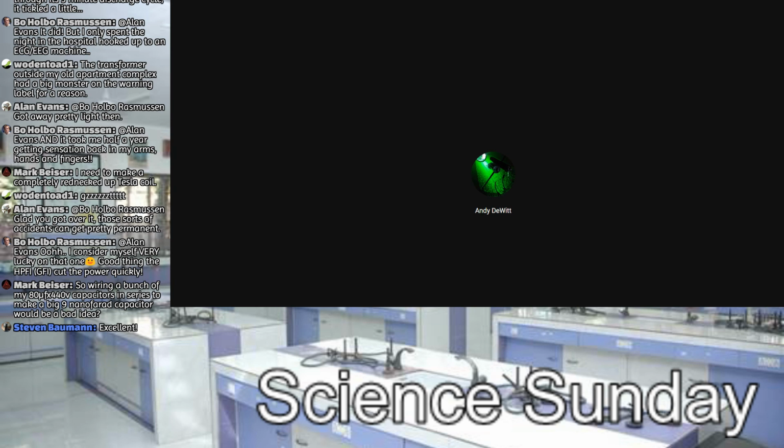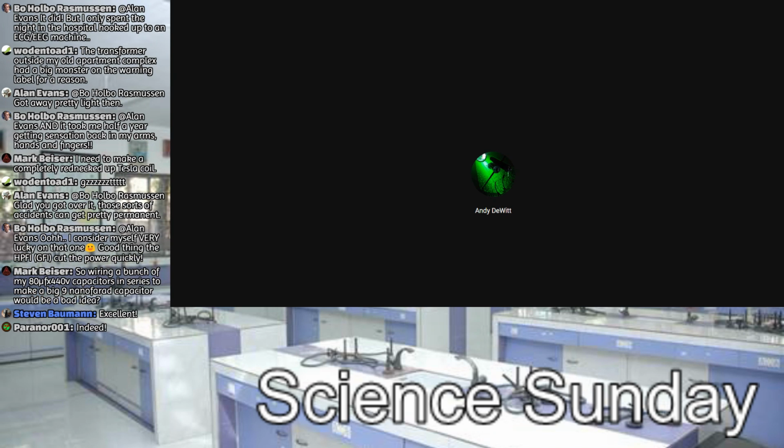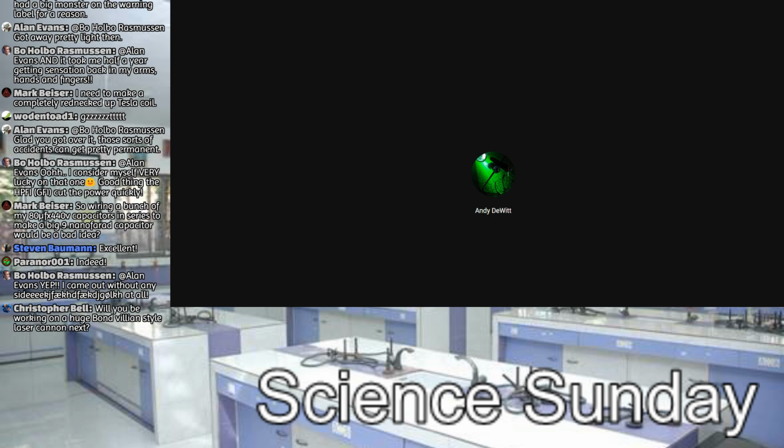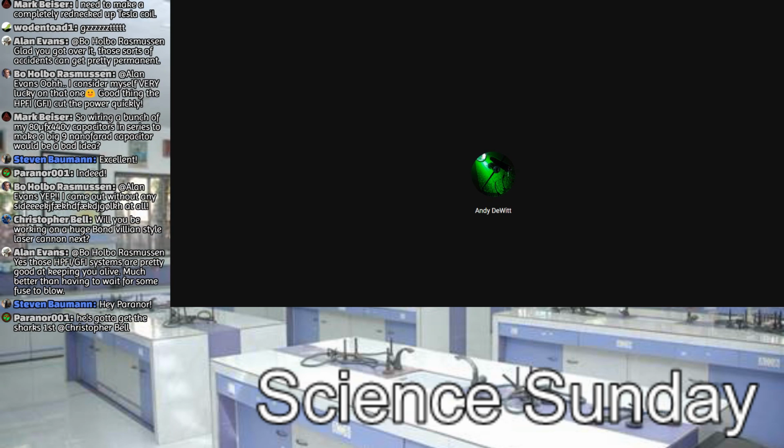The primary is supposed to be resonant a tiny bit lower, because when you fire the thing up, as soon as it makes the visible streamers, those streamers are conductive, and since they're coming out of the top load, and when you hear top load, think capacitor, everybody. They actually increase the capacitance a little and lower the resonant frequency of your secondary. So if you tune them exactly in resonance with each other, as soon as there's any discharge, they'll be out of resonance, and you get nothing. But anyway, that is the right way to tune one of these.